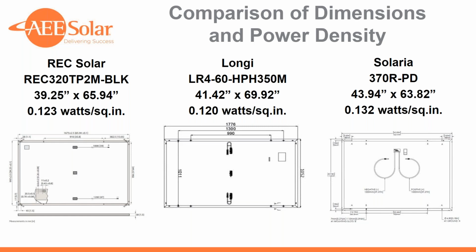So this shakes out to a module area efficiency of 0.120 watts per square inch. Again, it's a bit of an unfair comparison because we're talking about a brand new product for which the bins are going to come out on the low side. If we were to look at the middle of the normal distribution here, it'd probably be a 360 or a 365, and you might see the same watts per square inch.